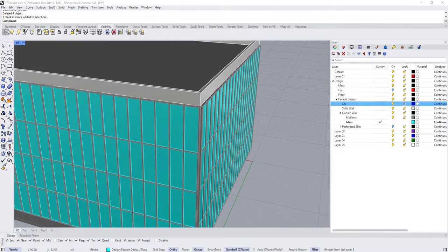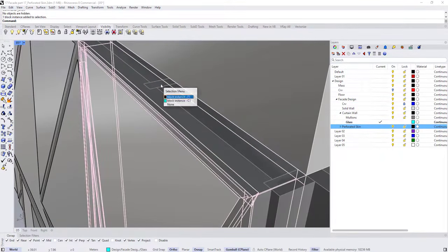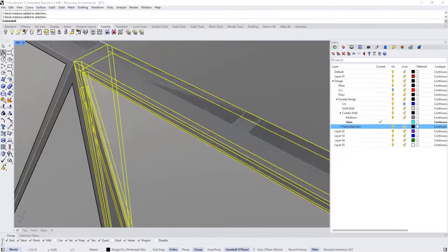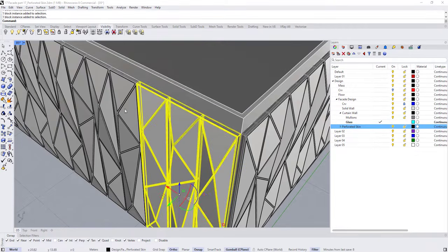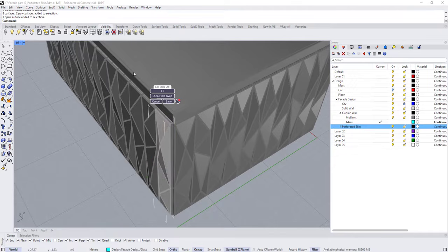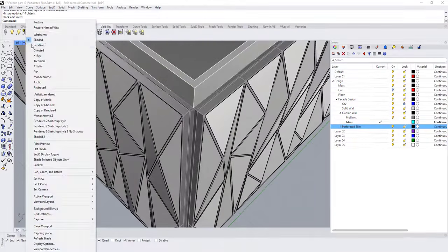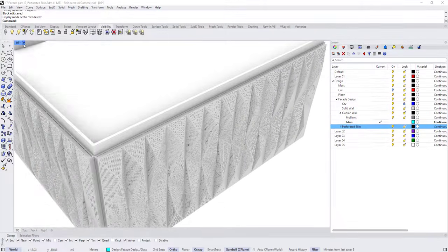By the way, now if we view the perforated skin, so let's choose the perforated skin. There's going to be, as you can see, some kind of overlap. This spacing is 0.2. So I can just select all of these blocks and move it away like 0.2, or I can double click here and select all of this. I'm going to move the object inside the block by a value of 0.2 to the outside. So now we don't have any overlap, and everything fits nicely.